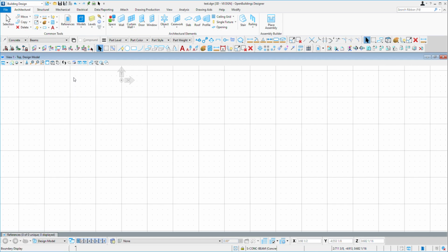Boundary Display is also useful. And Camera is also part of 3D modeling. Clip Back, Clip Front, and Clip Volume, these three items are also part of 3D modeling. When you prepare a 3D model in OpenBuildings or any other 3D software, these tools can be used. Construction: we have two classes in MicroStation and any Bentley software, one is Construction and one is Primary. I will explain in my next videos what Construction and Primary are, and how and why we can use them.